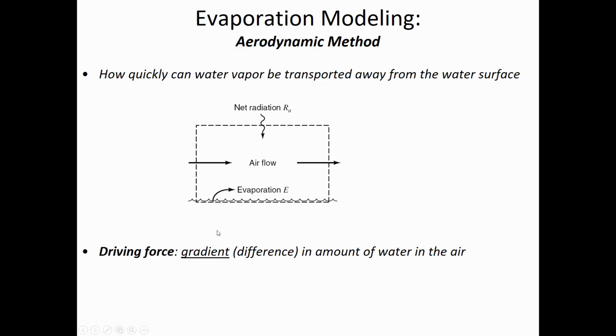And there's a gradient that is the driving force. The gradient, or the difference between how much water the air can hold and how much water the air is holding, is reflected by the rate. And so if the gradient is small, the rate is small.